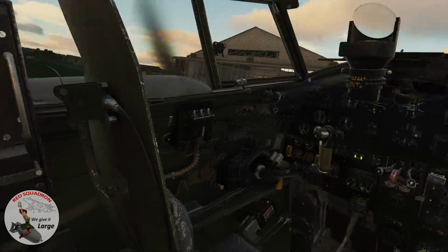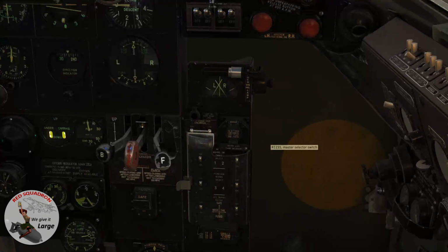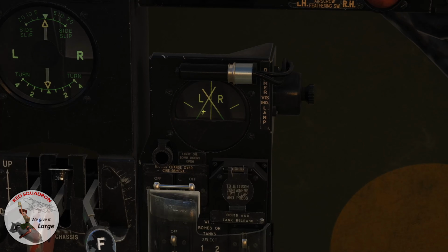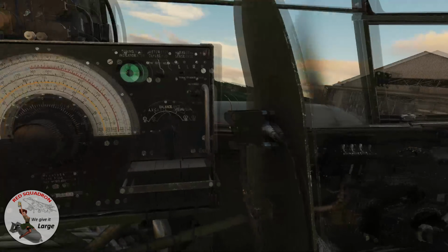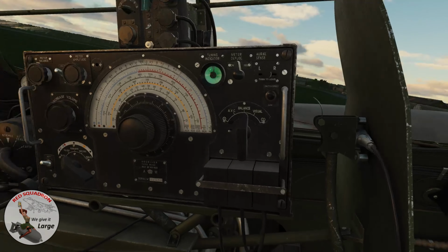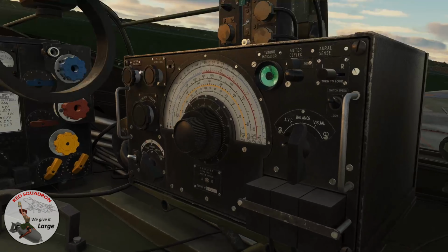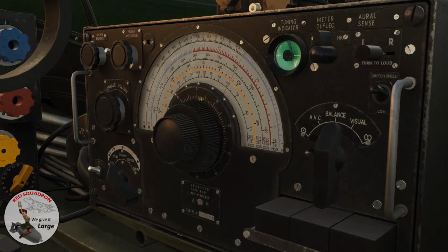Once that's done, if you look back down here, you'll see that the needles are crossing towards the centre line, but they're not quite over the centre line bang on, right? Which isn't very good for us, because then we lose accuracy as we're flying towards that frequency. So what we need to do is tune the needles in. We do this by adjusting the meter balance dial, which is up here on the top left hand side of the receiver. So I give that a little tweak,